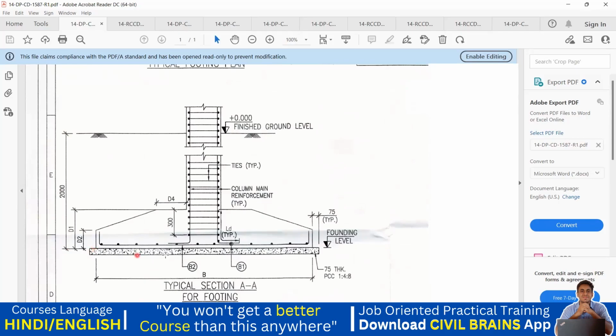Great. And now this is your PCC, 75 mm thick PCC, and it should be made up of 1:4:8 grade of concrete. Got it? And now since it's a slope footing, we know that we are going to get two depths. One is D1, which is the overall depth of the footing. Another is D2, which is only the rectangular portion. This is my rectangular portion. And after that, whatever I'm going to get, this top portion, it is a slope one.